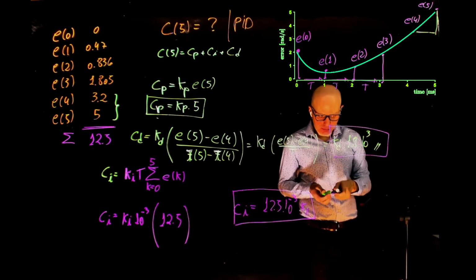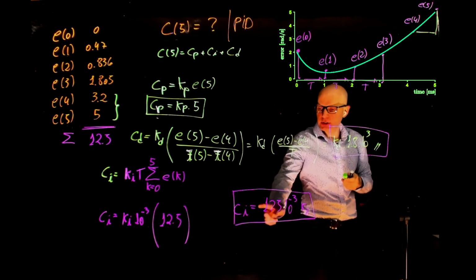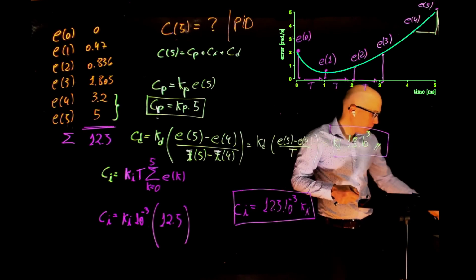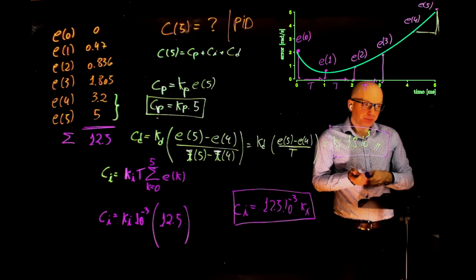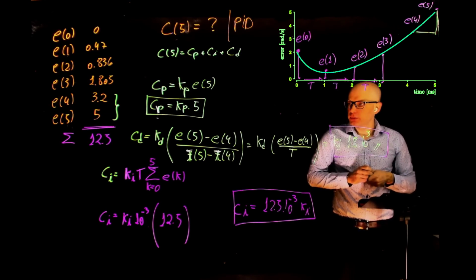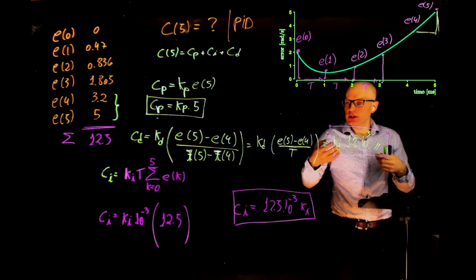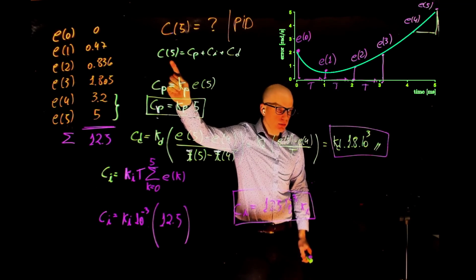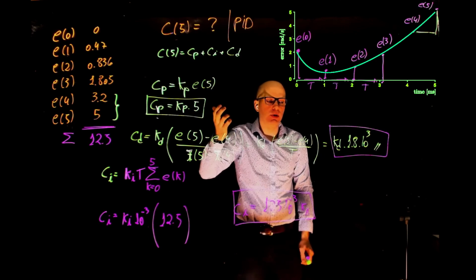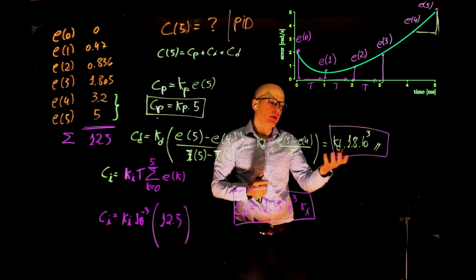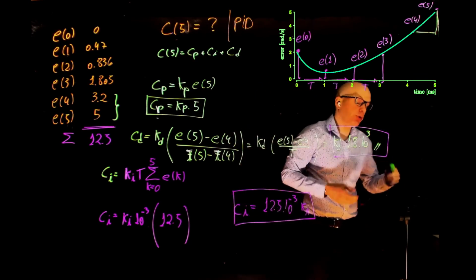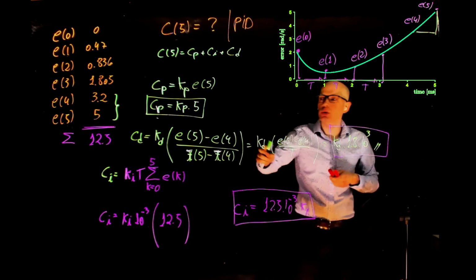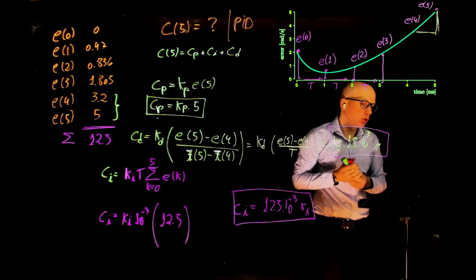If you're using an H-bridge, then you need to convert this scalar value that you see here, that now depends, of course, on Ki, Kp, and Kd, into a number that goes from 0 to 1 for the duty cycle. You need to map that from 0 to 1. That maps the magnitude, and then you need another signal that depends on the sign of C5 to determine if the rotation, in the case of speed control, would be clockwise or counterclockwise, or the voltage applied to the motor should be positive or negative. The duty cycle is related to the magnitude of this output. The direction is related to the sign of this controller output.